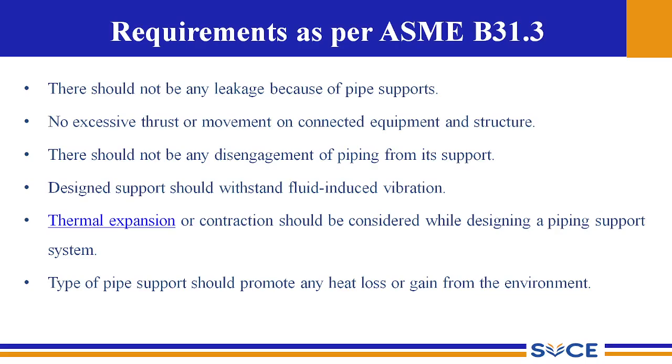Next is that after installing the support, there should not be any disengagement of the piping from its support. For example, if you are installing a shoe support for an inclined pipeline and we do not focus on the proper angle of inclination, then the pipeline will be disengaged from the support, and it can fall because of the action of gravity on the load of the pipe.